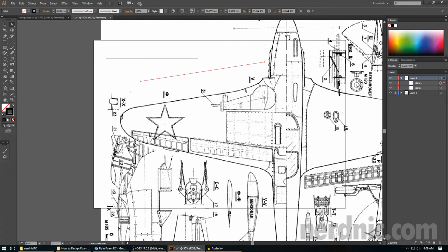Now, if you notice, I just picked up the whole thing. The other thing, again, if I press A, so I have A selected, but I don't have the line selected, and then I just go and grab the line, now I'm actually stretching it. You see that? So if I have the line selected and I have the direct selection tool, I will pick up the whole line and move it, even if I grab the edge sometimes. But if it's not selected and you grab the anchor, it will always just stretch it. That's a little tip there.